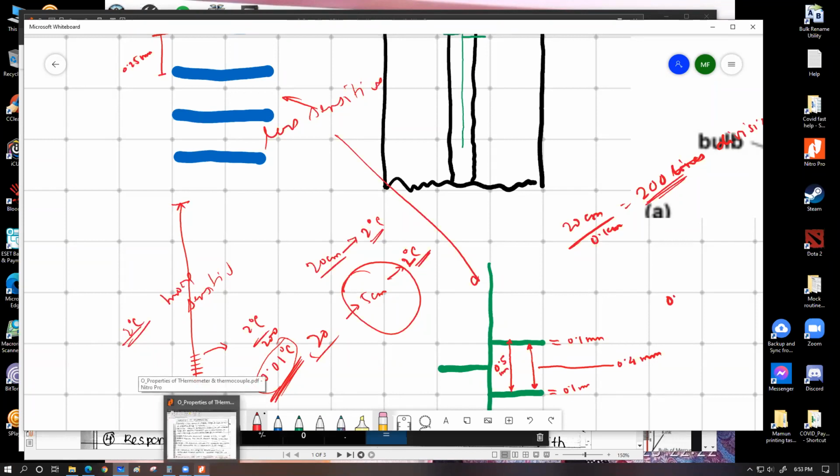So what we can essentially understand from this discussion is that the only preferable way to have a more sensitive thermometer is to make the length increase of the liquid inside the bore more for a small temperature change. That is the more practical, pragmatic way. For a thermometer that should give us a small height change or small length change for a certain temperature, attempting to draw a lot of lines within that small gap to achieve a high sensitivity is not a very practical solution, because that will limit the usage of that thermometer.